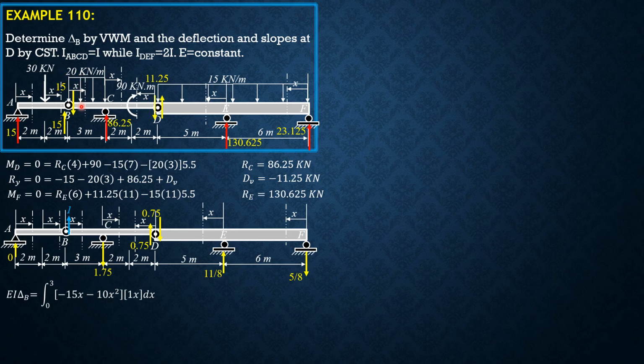That's for moment at this section, considering forces at the hinge as a reference. These are not included anymore because the reference is a hinge. This is a point of discontinuity for moments. Then in this section, the moment is just positive 1 times x as shown.